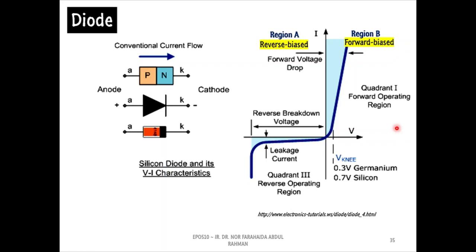flow in electrical circuits. If the current flows toward the anode terminal, the diode is in forward bias and it will turn on. According to the VI characteristic curve, in this condition, the diode can conduct high current from anode to cathode with a small voltage drop.